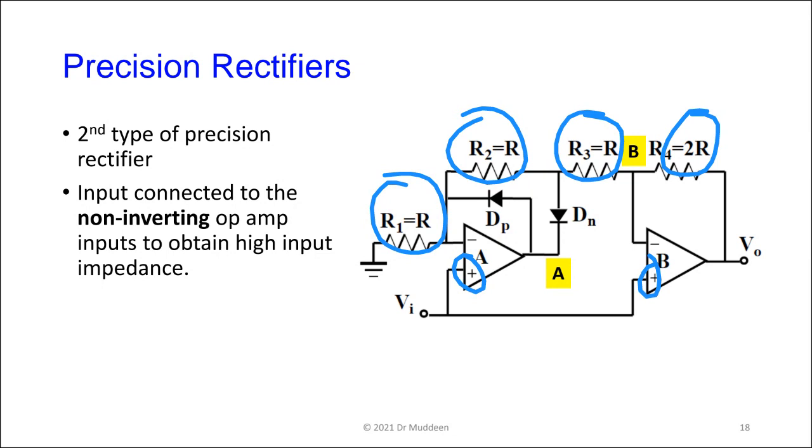Now, one of the things we know immediately from the behavior of op amps is that the input impedance of the non-inverting configuration is more than that of the inverting configuration. The input impedance of an inverting amp is simply that first resistor coming in, R1. Typically, because of the gains we normally have, like a 10K, 15K, 20K there, the input impedance is quite low. For the non-inverting amplifier, we are sending the input right into the non-inverting terminal.